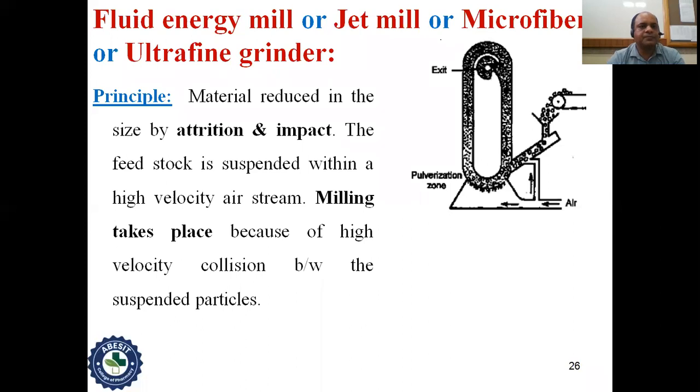The principle of the fluid energy mill is that the material is reduced in size by attrition and impact. The feedstock is suspended within a high velocity air stream in which milling takes place because of high velocity collision between the suspended particles.